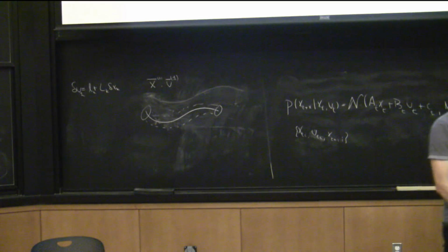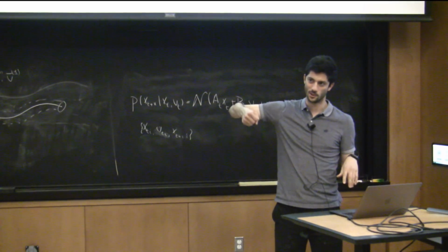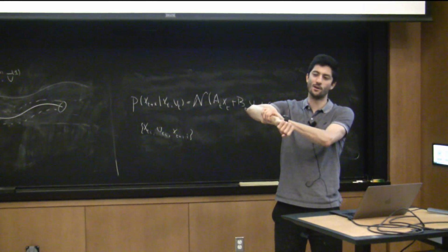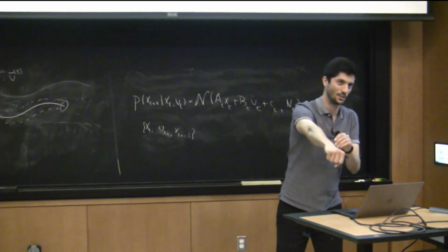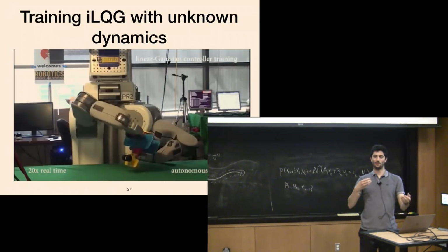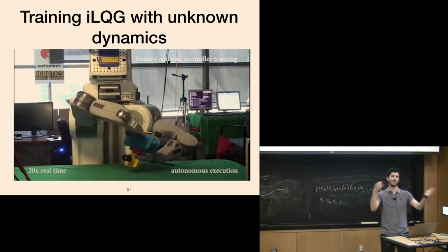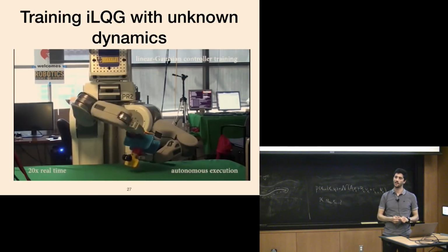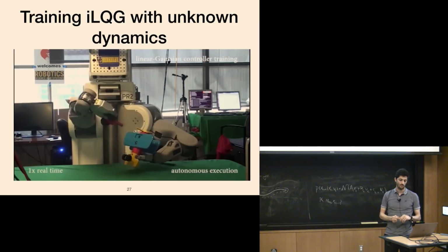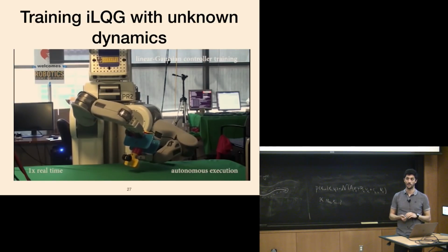And also, because it's this time-varying linear, suppose you did start from the same initial condition, but I go in there and hold your arm for like 2 seconds, and then I let you go. It probably won't work either because now these things are really indexed to time. So they might be wrong, even though you're on the trajectory, you're at the wrong time. So this works really well, but you are optimizing a local controller here, right?